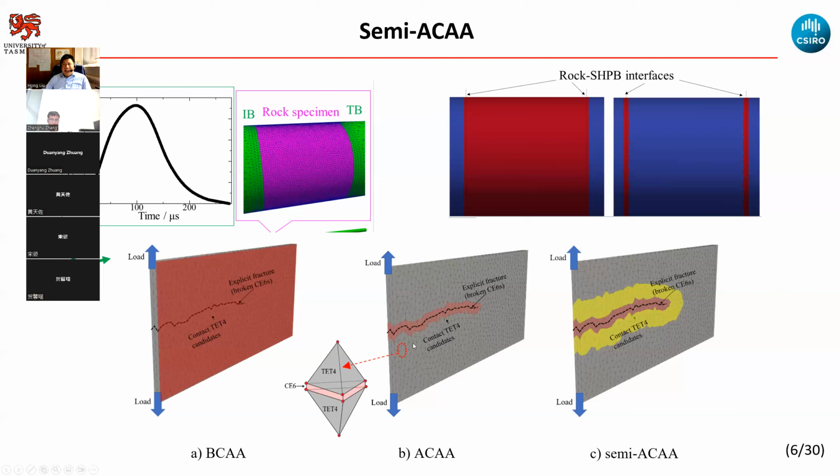For your case, if you have a crack formed here, in the adjacent region or in front of the crack, the material has not completely failed yet. The damage variable has not approached 1, but it is already bigger than 0. So you have macro damage there.